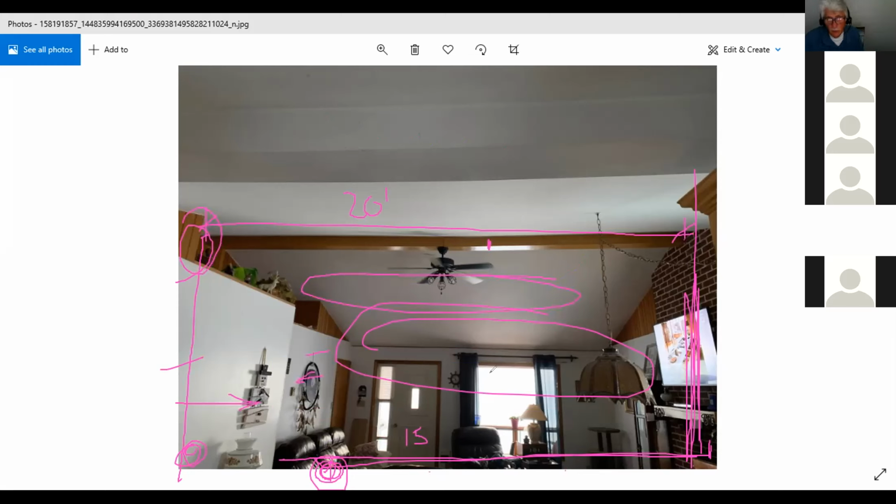So that's why it's important. The key thing that I'm trying to stress here, Brandon, is that geometry is everything. You understand? So drawing an existing plan is key to making sure you don't make a mistake. I know that you were drawing the modifications because you want to see what it's going to look like modified, but before you get there, you have to see how structurally it can be modified. If you weren't going to touch the structure at all, fine. But since you do want to remove a column, it's very important to know how the existing structure is behaving right now.